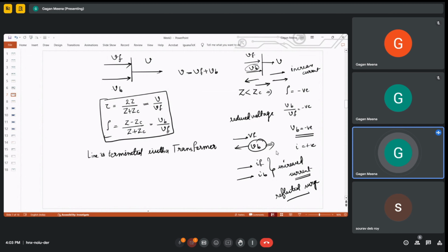We have seen what happens to the resistance in the open circuit and short circuit. Now what will happen if the overhead line is terminated by a transformer? The impact of a high voltage surge on a transformer is similar to what happens at high frequency: the distribution across each winding is modified due to the capacitance between the transformer windings, between the turns of each winding, and between each winding and the grounded iron core.